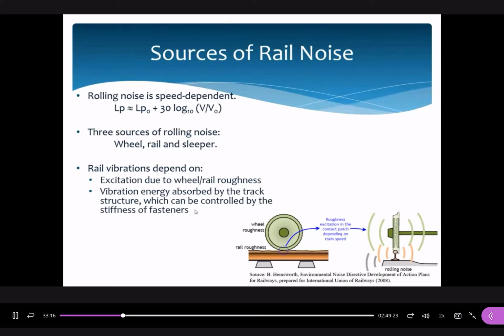Along this line, it means that we have 2 forces. The first one is the transmitted force, another one is the external force. If you consider that this is a simple structure with damper and with mass, and you apply a force on this system, Ft is the force transmitted to the surrounding environments. In this case, we want to reduce Ft, the transmitted force. If we can control the transmitted force, it means that we can control the structure-borne vibrations, correct?